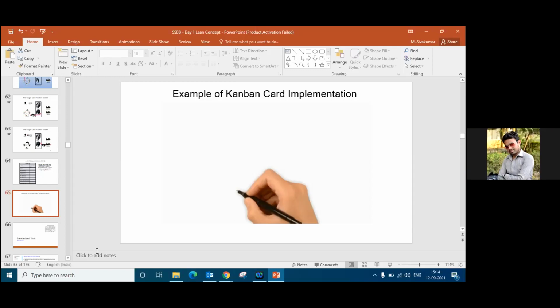Yes, so waiting is another loss. Again, it is another opportunity for improvement. Correct, sir. Before the last bin becomes empty, it should be ordered, and the system works like that. The card shows the information. There is a limit on the card: if the quantity is 20, then after 15 are used, within the last 5 quantity the supplier will be informed to refill the container.